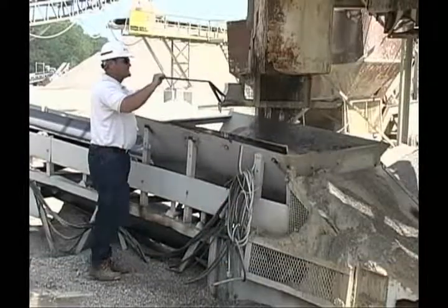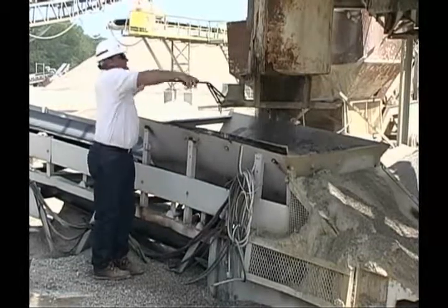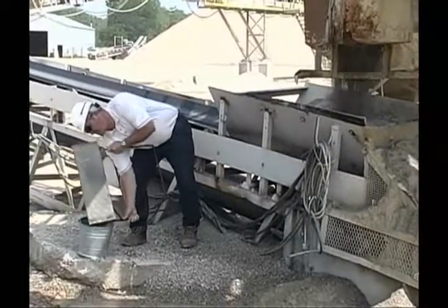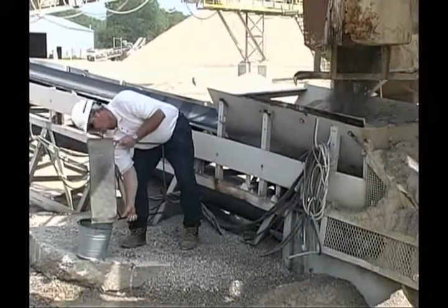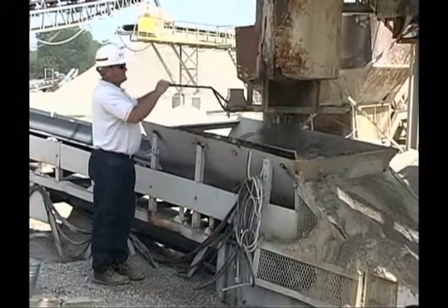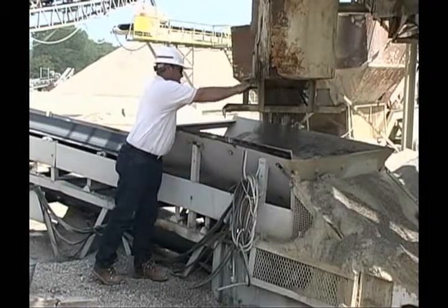Some production plants have devised their own methods to intercept the stream flow of material. This usually consists of a catching device on a slide or rollers. These devices slide through the stream and work quite well. If you encounter problems locating a good safe area to take a sample, consult your materials office for direction.